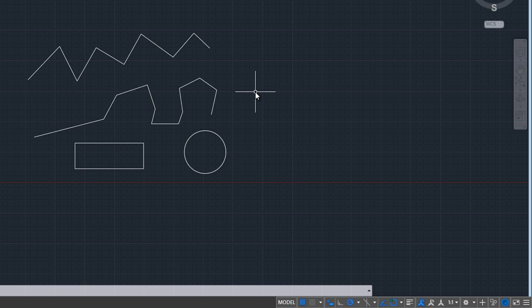So you can set up the drawing limits, okay, if you are finding this a hindrance, by using the limits command. However, and this is noted as a hack that I do, I find that I never need to set up these window limits, okay, when I start to work on a drawing. The only time that these limits affect my use of AutoCAD is when I'm in the process of drafting and AutoCAD limits what I can view.